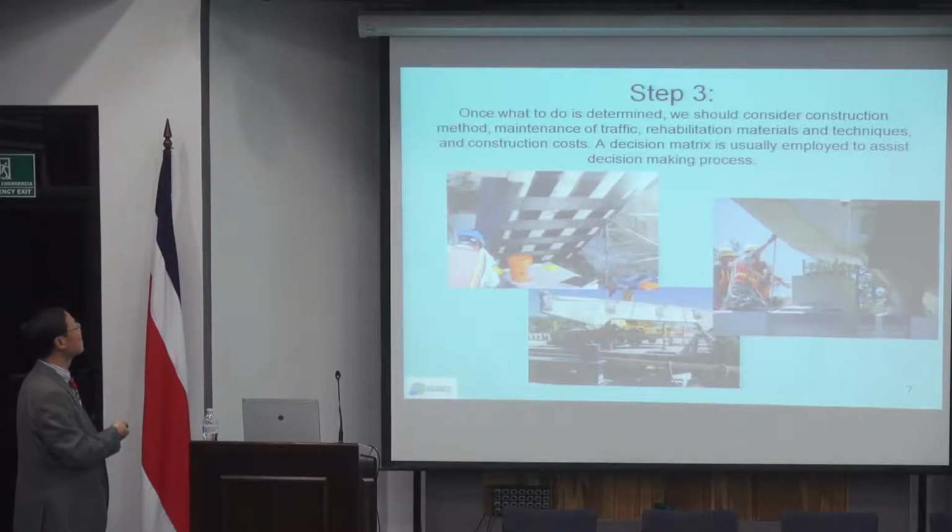And these are the constructions. They use an FRP strip for longitudinal reinforcement, and then use that strip transversely as shear reinforcement. Some areas near supports need large shear, so they actually wrapped them solid. And they tried to use precast, which looks the same shape as the original.